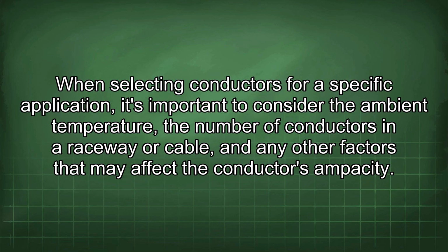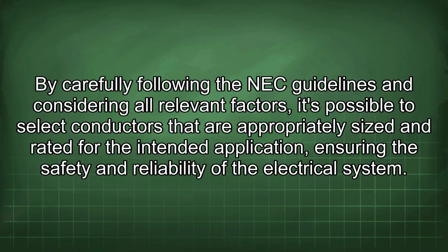When selecting conductors for a specific application, it's important to consider the ambient temperature, the number of conductors in a raceway or cable, and any other factors that may affect the conductor's ampacity. By carefully following the NEC guidelines and considering all relevant factors, it's possible to select conductors that are appropriately sized and rated for the intended application, ensuring the safety and reliability of the electrical system.